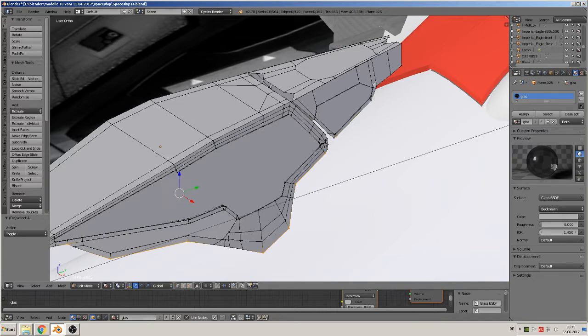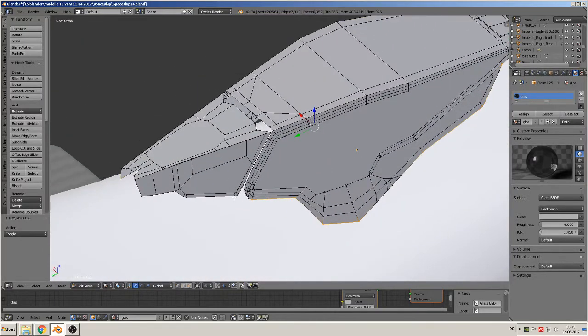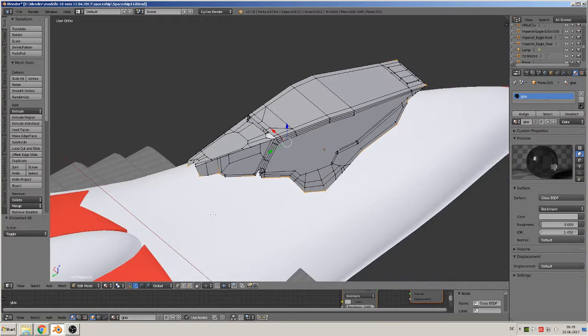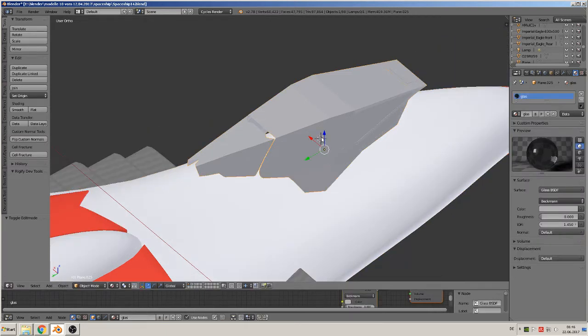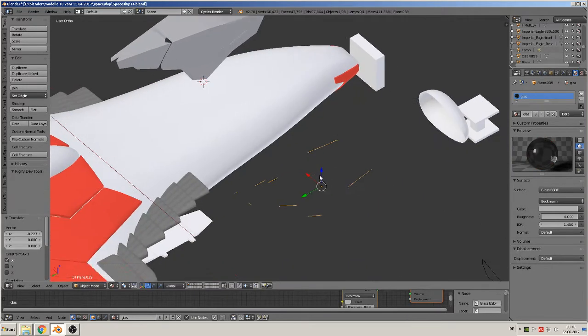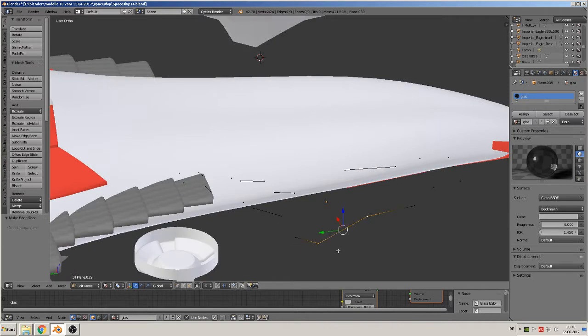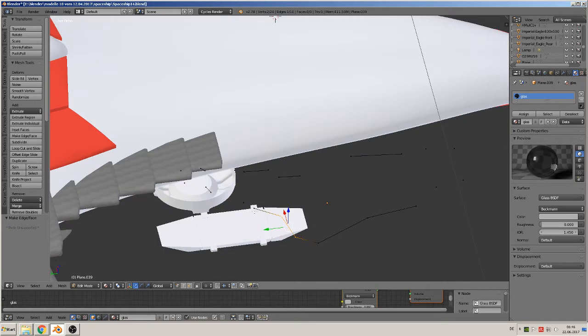And then when we have that outline, oh, not that, that, and that was that. Good. Shift D, then P to separate the selection. When we now move it away, we have here our cuts, and that we must now bring together. So that means we have to connect that with F, that with F, and so on, until all points are connected.